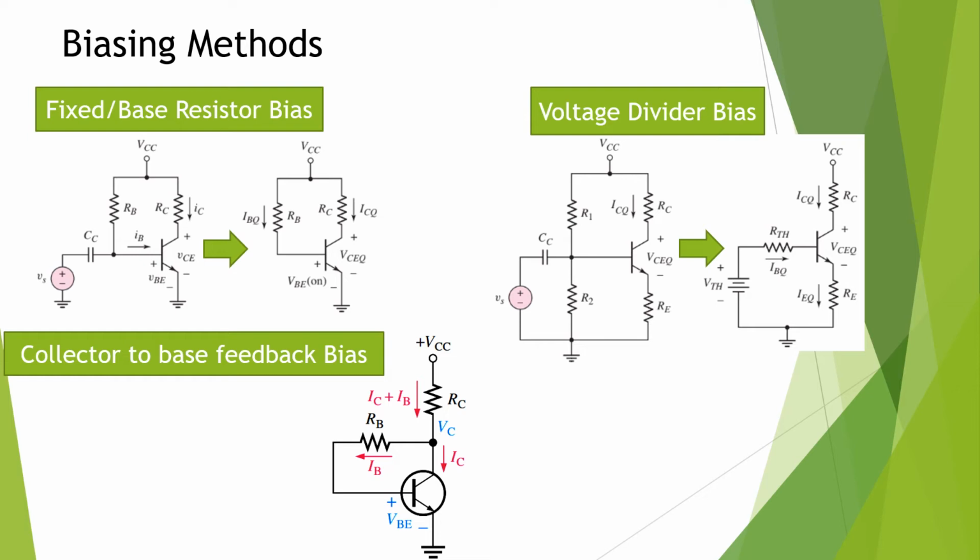Next we are going to see the small signal analysis. Before that, we have to know that all these biasing methods are only for making the BJT operate in active mode. But due to temperature changes, even though we design the circuit, there is definitely a change in the Q point. So how do we stabilize the Q point? More stabilization methods are available to stabilize the Q point.